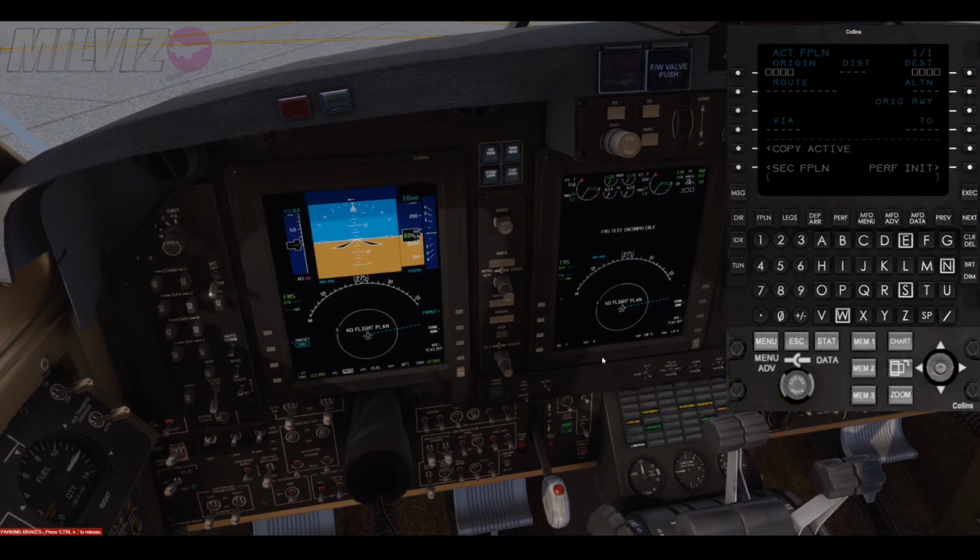Well, I could be a couple miles from the airport reference point, and it's going to take the FMS quite a bit to resolve that position back down to a 1 nautical mile active navigation performance. If I took off and I was more than a nautical mile, then I could exceed the required navigation performance for my takeoff. So because of that, Rockwell Collins recommends that we just accept the GNSS position.